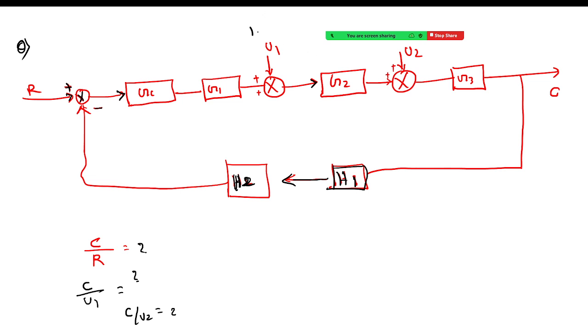There are two loads, right? This one is the first load. This one is your second load. R is called the set point. Here it will come and generate an error, right? This error will move forward, see the load, and go to G2. Again it will see the second load, then come out and give an output C. C is the output, and it is taken back to the input with negative feedback, generating the error, so it keeps running in a loop, right?